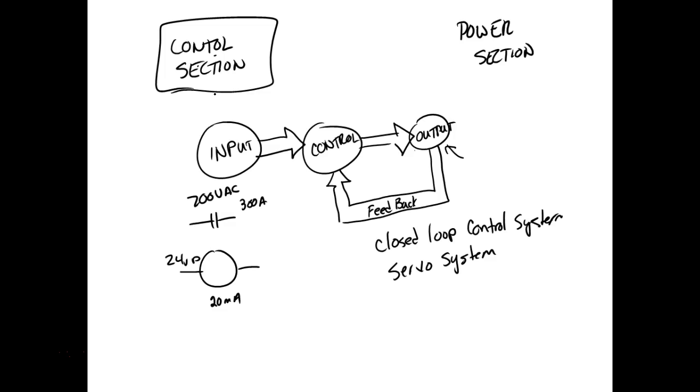So the PLC could bring in a what? A relay. The relay's in the control section, but the contacts could be controlling stuff in the what? In the power section of the system. You understand that? So PLCs do not do away with relays, because a PLC cannot run a 200 horsepower motor. But a PLC could pull in a relay, and the relay could run the 200 horsepower motor. So all your motors and big stuff like that are over in the power section. Then your PLC's controlling that usually through a relay, right? That makes sense.